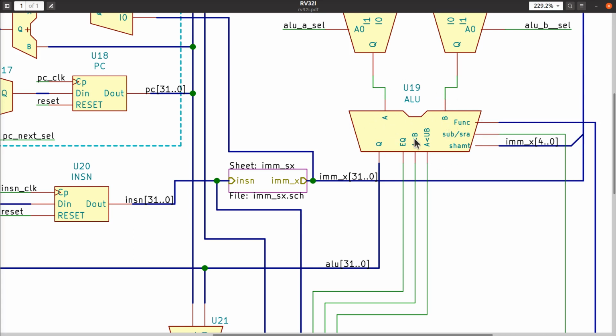We discussed that before. What I have not discussed before is the operation of shifting values. Let's just assume that shifting is just yet another combinational circuit that has a truth table. You can work all this out by hand, and it should come as no surprise that you can implement a shifter using a large number of multiplexers.